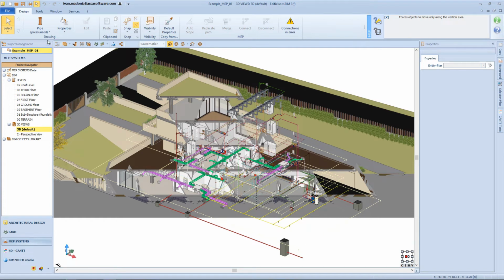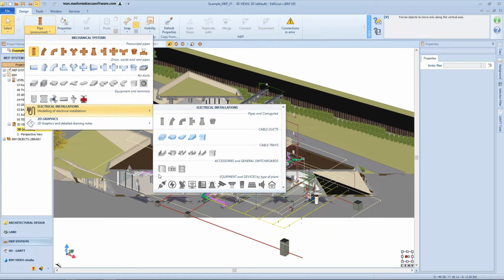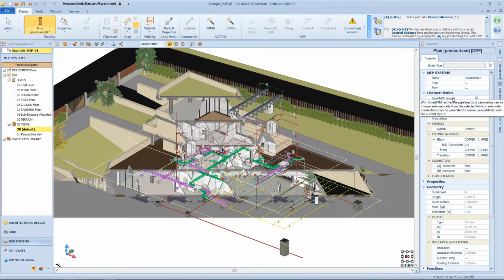When you activate entities such as pressurized pipes, other pipe types, air ducting, cable trays and pipes for electrical distribution etc., the Characteristics section appears in the Properties toolbox. This allows you to assign the material, the profile, size, push-fit fittings, and other piping-like settings.